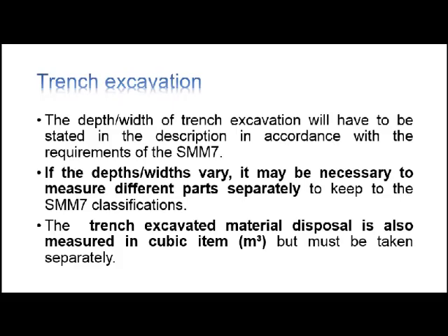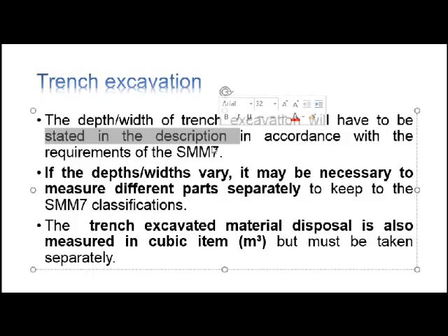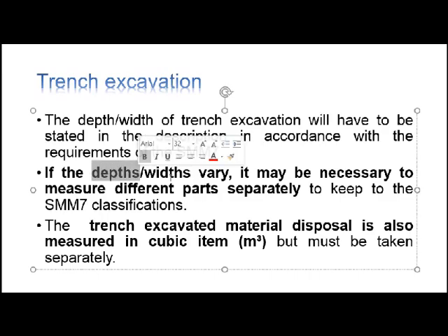Okay, let's define further what is trench excavation. Okay, when you want to state the description by using your SMM7, you should identify what is the depth and the width. Okay, because in your drawing, perhaps you might have different types of trench depth and also different types of trench width.